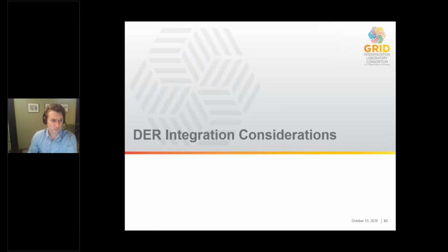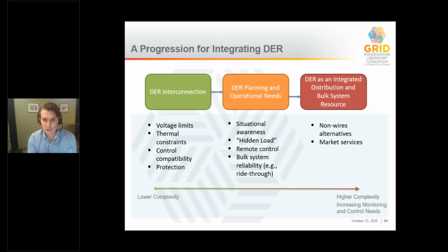Yeah, next slide, please. So very briefly, when I think about a progression of integrating DER, in my mind, I break this down into at least a few different steps. Initially, there's really the physical connection and making sure that for how that device is connected in a normal operating mode, that there aren't going to be thermal protection or voltage types of issues.